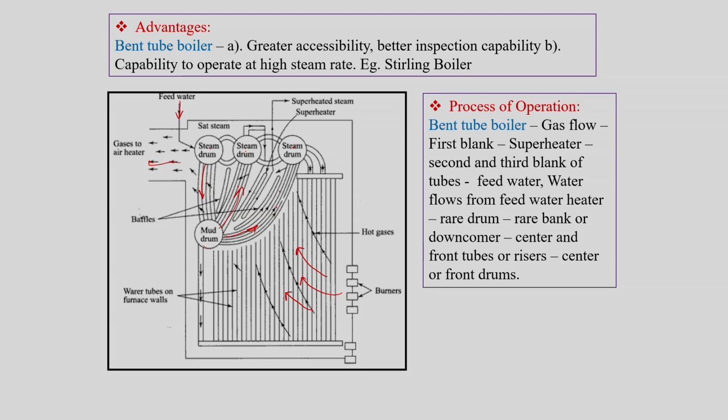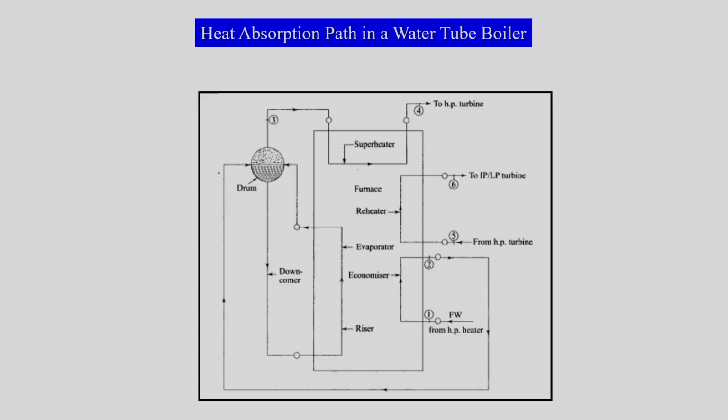However, intermediate to these evaporator tubes we have superheater tubes also placed. In general, at gross, the arrangement of different tubes in the boiler or the steam generator is like this, where we will have the water, and the flue gas which is coming from the top will heat the superheater, and then it will heat the reheater, and it will heat the economizer at the end, and this is the wall of the boiler.